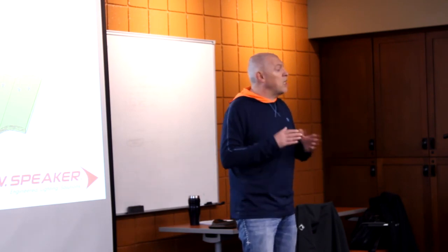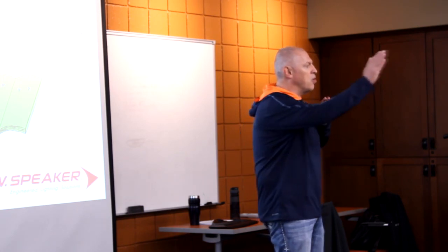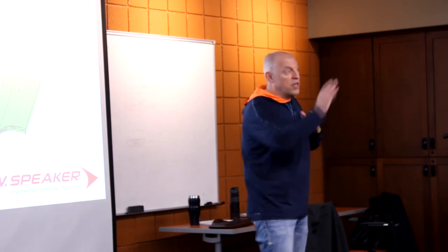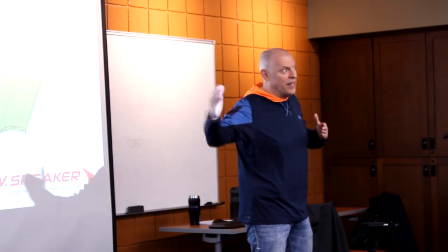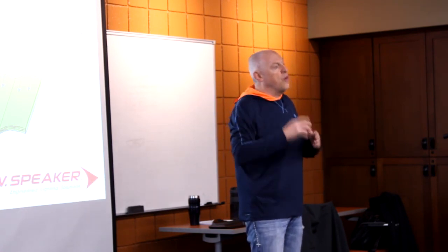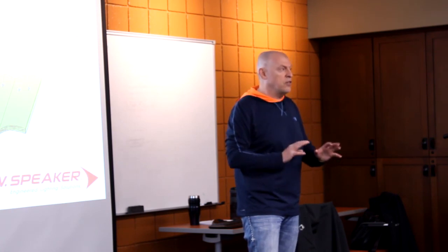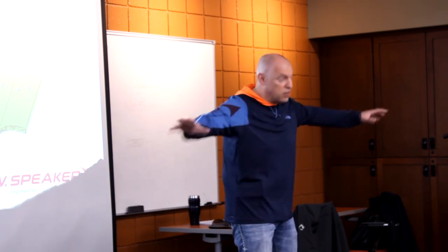For a headlamp, especially high beam, you really don't care so much about lumens as you care how far you can see. And how far you can see is really a candela measure. For a low beam, which is a mix of things, we're using the lumens or lux. For a high beam, it's more candela because it's directional, versus a location on the surface that you can see.